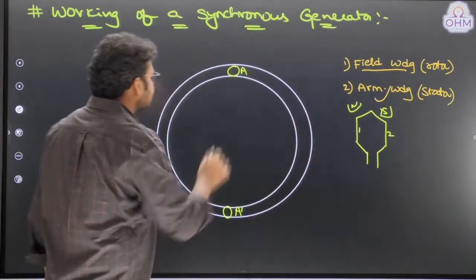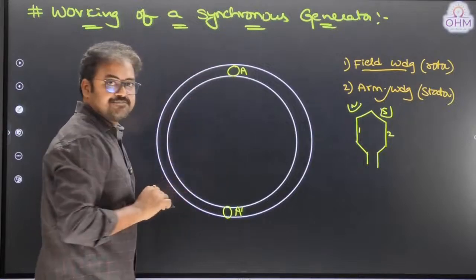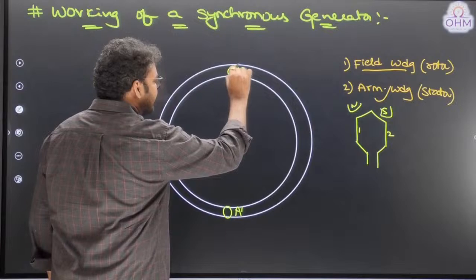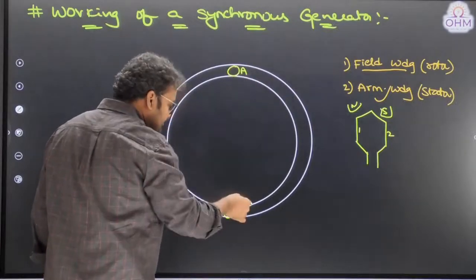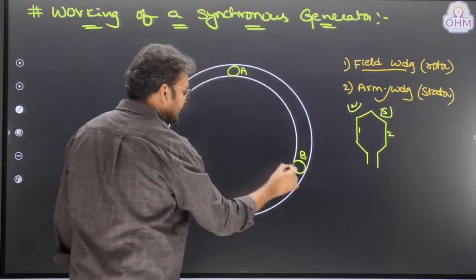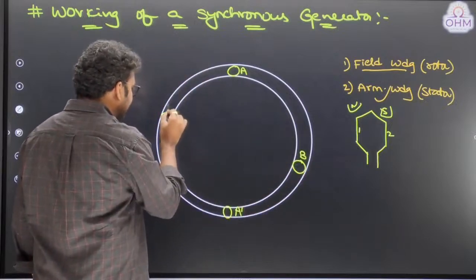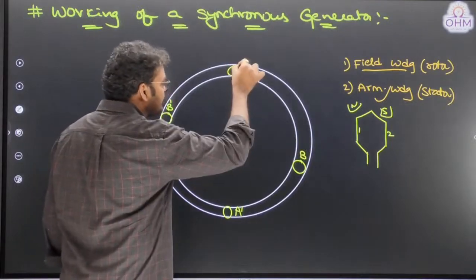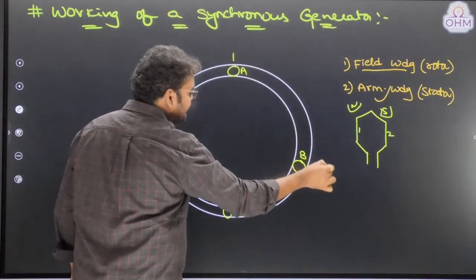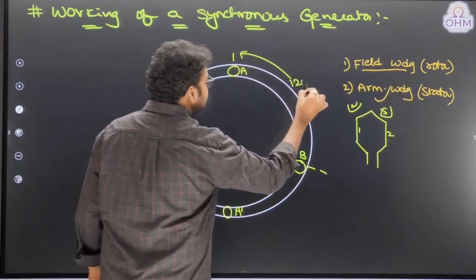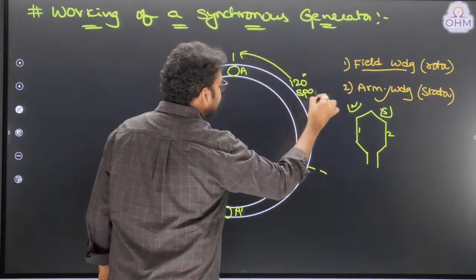Right. So this is where phase A winding started. Now next, phase B winding. See this is 180 degrees. After exactly 120 degrees, you have to wind phase B. And opposite side, we have B dash. Correct? So what is the angle between A and B if I ask you? That is 120 degrees. From here to here, if you calculate, 120 degrees. This is what we call it as space angle.